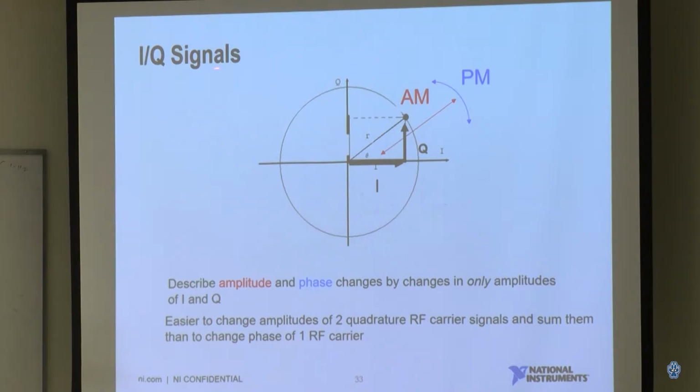What the constellation diagram means: when you have an I and Q signal, it represents a dot. When you transfer multiple I and Q signals, you have multiple dots in your constellation diagram, and each dot communicates with the others. The more dots, the higher the signal transfer requirement, and the higher the bandwidth.